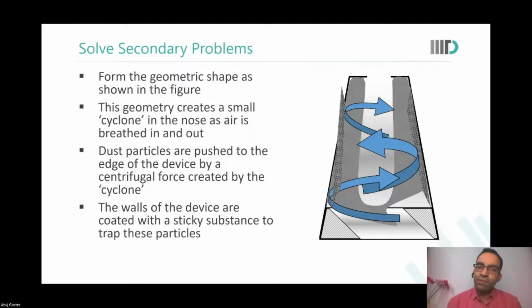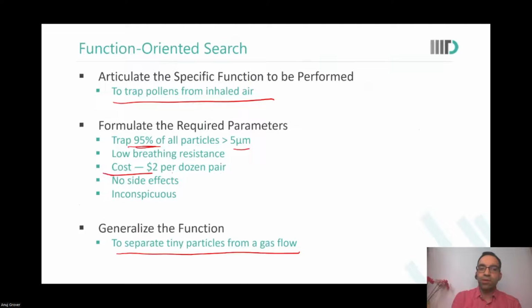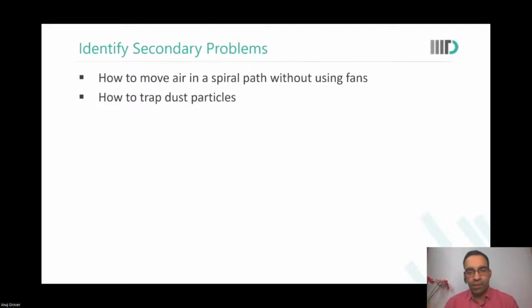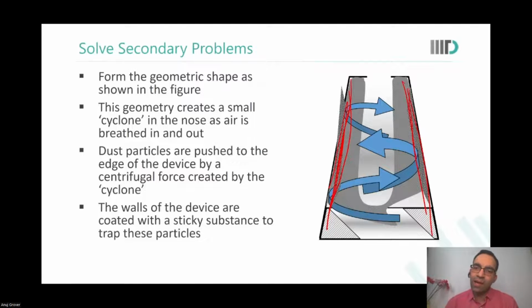And the geometry of the filter creates a small cyclone in the nose itself. The dust particles are pushed to the edge by the centrifugal force, because you're reducing the radius of the movement, and the walls of the device are sticky. So the particles will simply stick here. And you notice we had kept the cost to be extremely low. So now you don't need to clean this nasal filter up. You just throw it away. They are disposable, something like masks. You dispose of the mask, so you just wear the next nasal filter when you go out next.